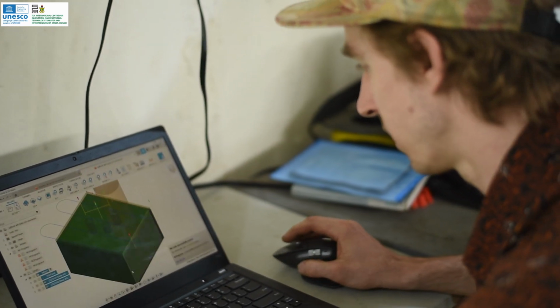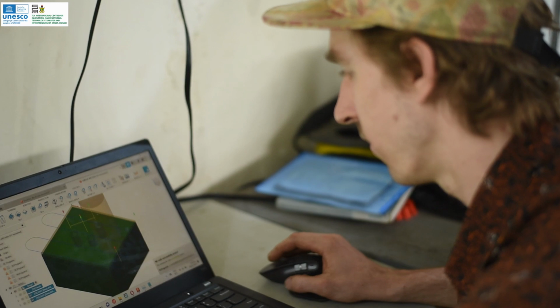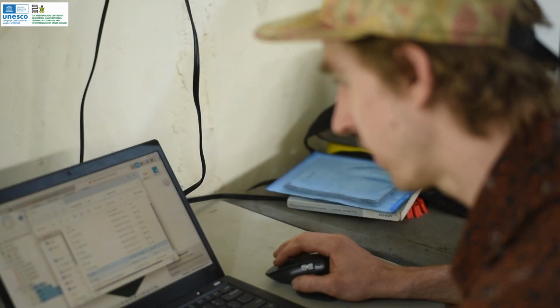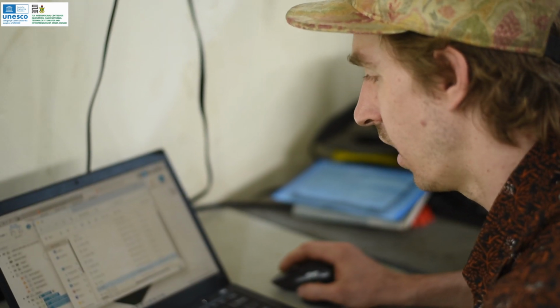And we'll hit post. Once we have, this is one other thing we have to go and change. If you ask the distributor for this machine, they'll tell you in order to run G-code on the GSK machine, you have to, in their words, change something in the header and at the bottom of the G-code.